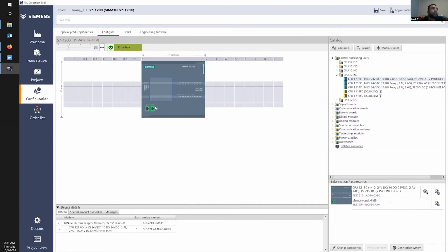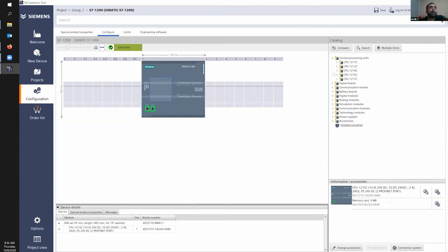The nice thing about all new devices from Siemens, most of them, I think every device now, is they all have Ethernet with 2 Ethernet ports. They are not separate IP addresses, but they are just switched. So what you can do is daisy chain your Ethernet cables and just create a ring, so it helps out. Let's go ahead and look at all the IO card options.